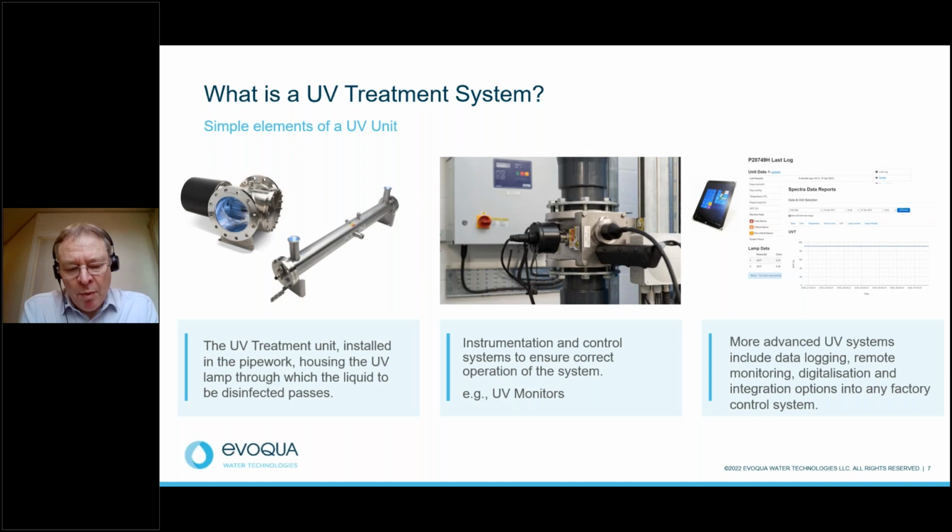And again, in both these cases, when we talk about pressure, we're not referring to water pressure. We're actually talking about the internal gas pressure of the UV lamp. So that's an important distinction. In terms of the terminology for lamps of pressure, that should be seen just as a type of lamp. So again, in general, the selection of the UV will depend on key parameters for the installation. Are we space restricted? Do we need particular treatment applications, such as for chemicals or for adenovirus or certain organisms, or do we need power efficiency? So again, the selection of the unit is very much dependent on particular installation conditions.